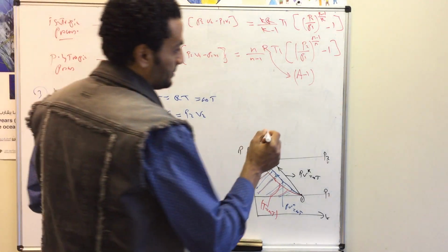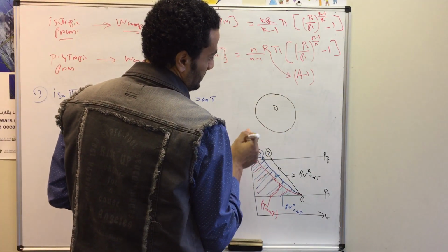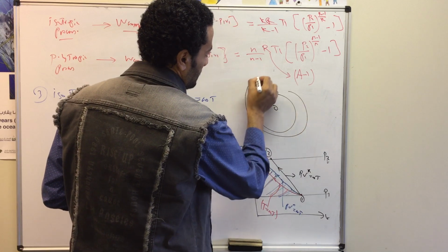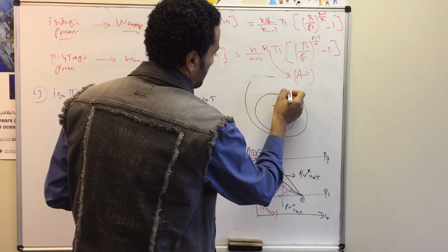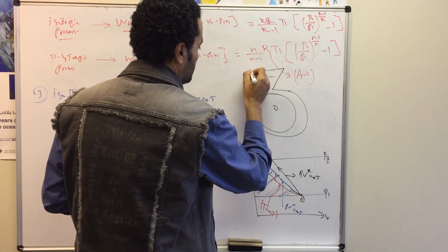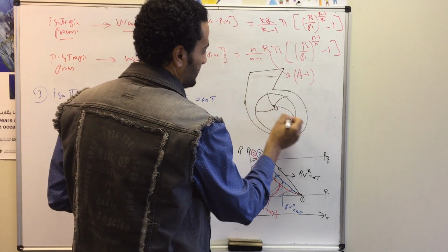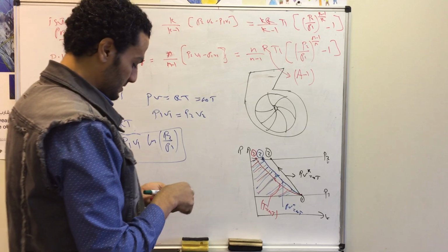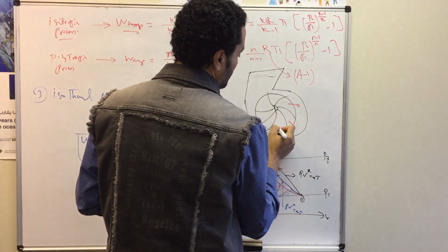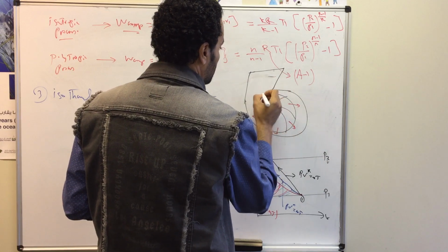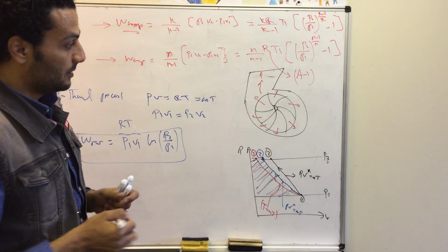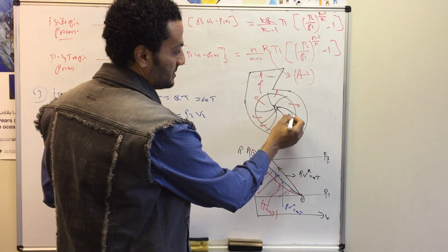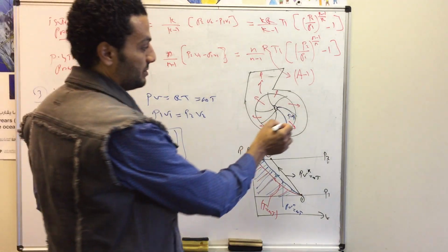But if you look at the compressor, those are the plates of the compressor. The design of a centrifugal compressor is something like this, and the blades are here. The flow is coming into the compressor normal to this clapboard, and then it is leaving in the radial direction between those two plates, and then it is collected in the casing and leaves the compressor. While going through those plates, the area between the plates takes the shape of a diffuser, so the pressure is rising between the plates, and the temperature will also be rising.